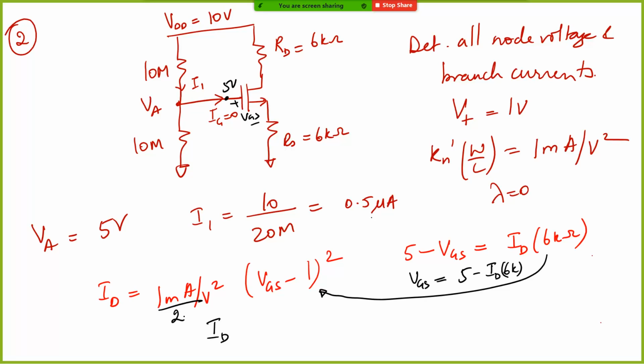So here also we have assumed saturation region and then we are backtracking. Correct. Actually, that's another point that I missed telling. Here what you do is you assume saturation region, and then you evaluate it and finally verify if your assumption is true. There will be some problems in the exercise or in the textbook where you will work it out and get some very absurd or unrealistic numbers, and then you know that basically your assumption was wrong.